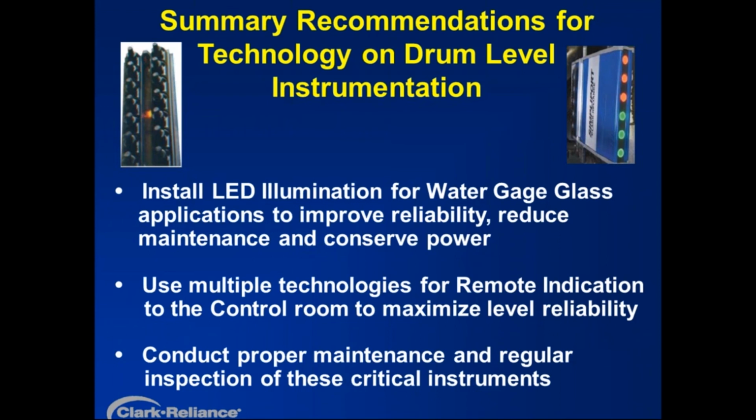Conduct proper maintenance and regular inspections of these instruments. Look for leaking valves, missing insulation, deteriorated level instruments. Any obvious flaws should be taken care of before any damage occurs, whether it be steam cuts or personnel risk.